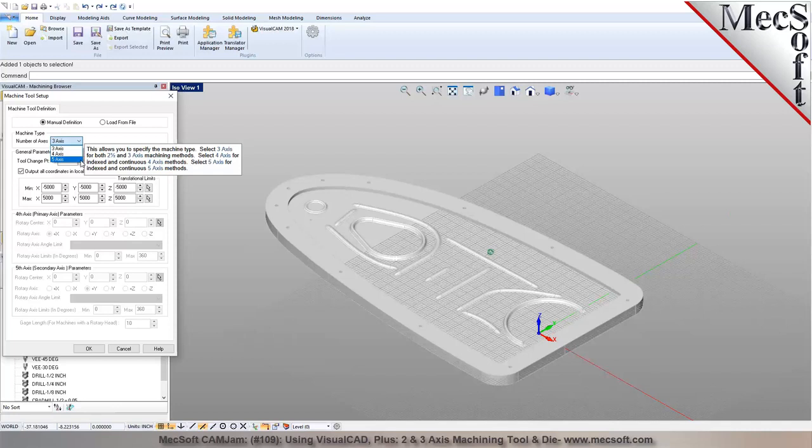So if you just have a 3-axis router and you need to machine the part from multiple orientations, you can do it with the Pro by creating multiple setups. But if the router is capable of 5-axis, then you can orient the head to different orientations and then machine them from different planes or different orientations as well. So that's what's called 3+2 machining or index 5-axis. Now, if your machine tool has an automatic tool changer, we automatically output tool changes, and it calls out the tool number and then whatever your code is, like M6 or whatever it is, to call up the tool.